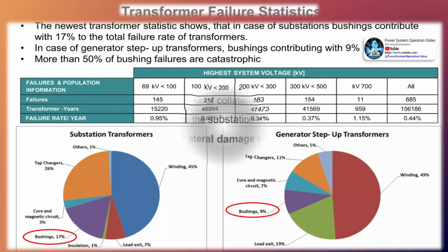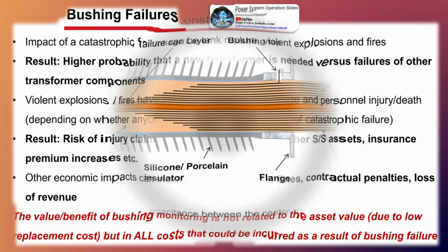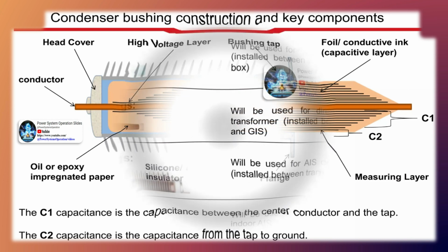Bushing monitoring system advantages. Early detection of a degradation of bushing insulation and internal layer breakdown. Monitoring power factor/dissipation factor and capacitance at nominal voltage. Applicability for condenser bushing type and other OEMs. High accuracy measurement can be achieved by using parallel measurement of up to 6 bushing leakage currents. Optimized and purposive maintenance strategy reduces outage costs. Comprehensive online condition monitoring system possible for transformer and bushings, in combination with transformer monitoring and diagnostic system.